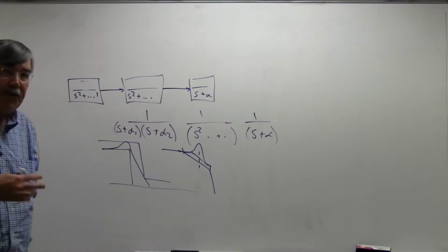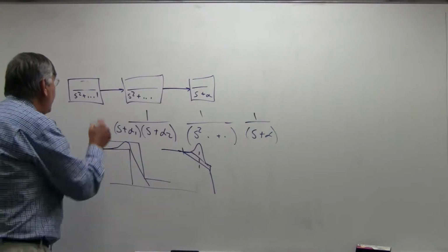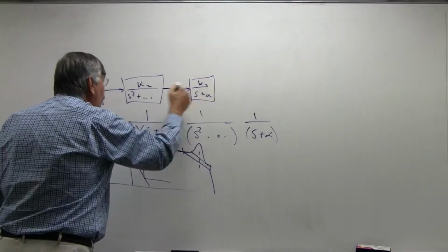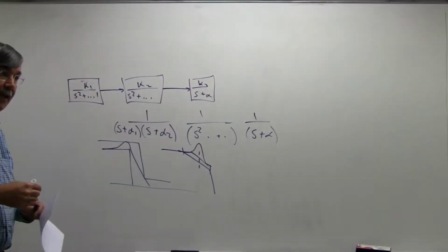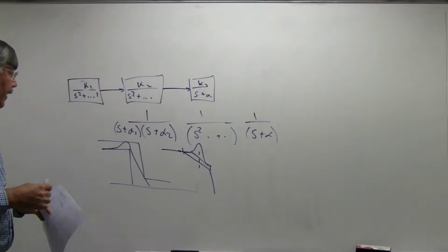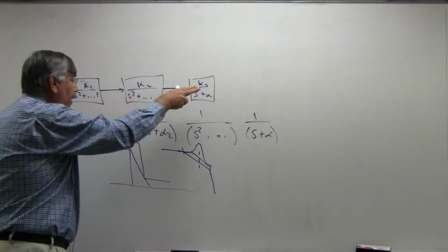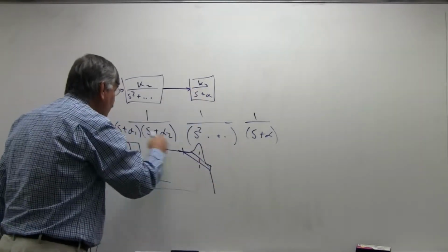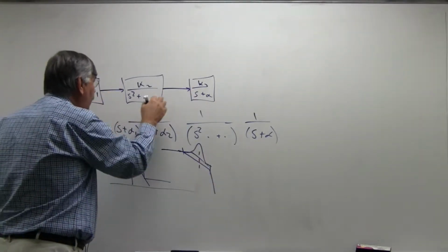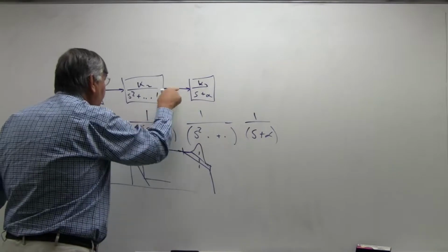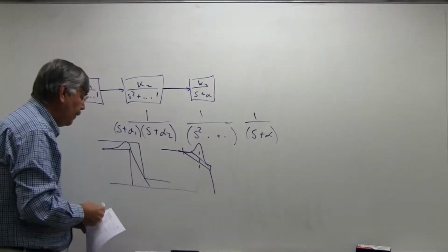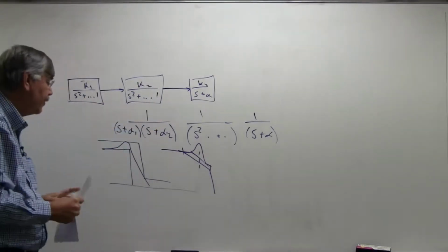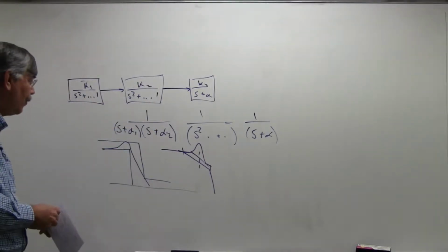Now, I just put ones in the numerator. If you remember, if we have constants in the numerator, and it's all poles like this, then that will be a low pass. And again, you can go through and see what happens at S equals very high frequencies. The S's start to drop off. When S is very small, then the constant terms out here would be the things that become important. So this thing is going to pass at low frequencies, and at high frequencies, it'll stop. So we've talked about that before.